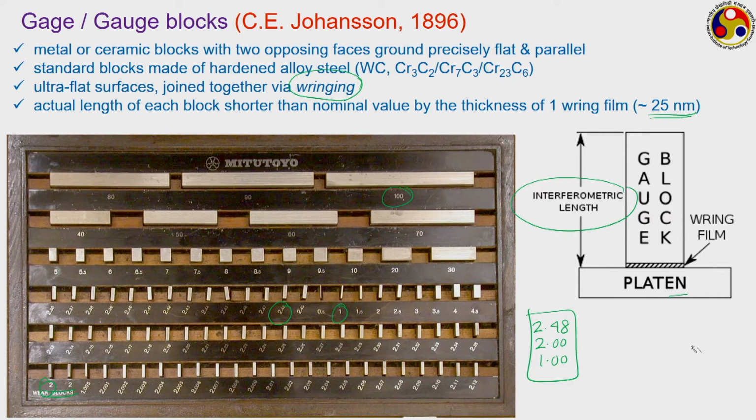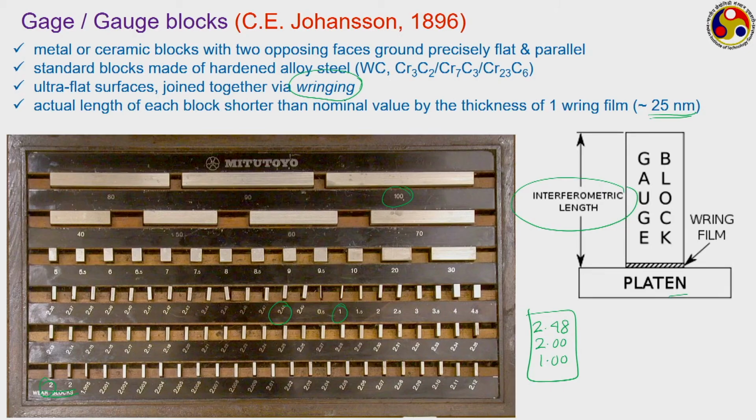So, we can join these three blocks and get the final value, or if we are trying to measure the value of any unknown dimension, then we can keep on stacking these blocks one on top of another and try to match until we get the exact comparison. So, finally, adding the values of these blocks, we get the final dimension.